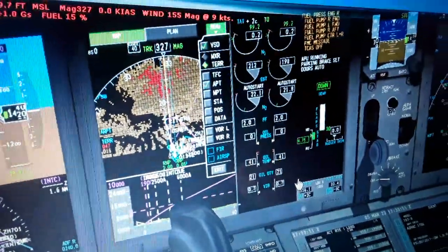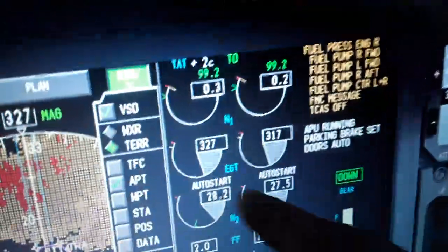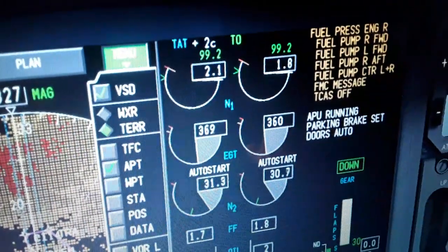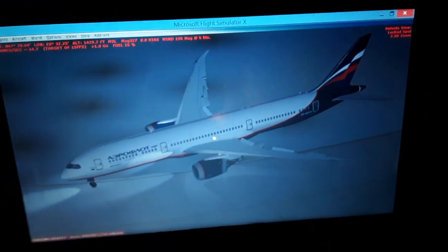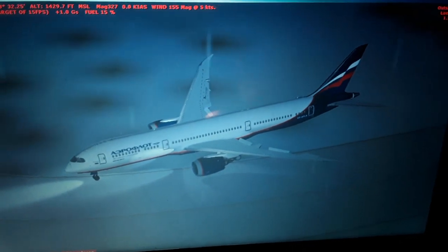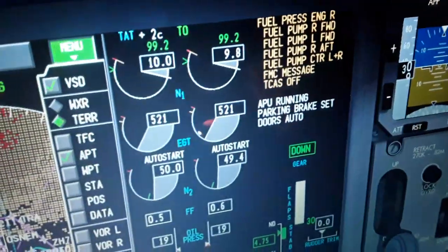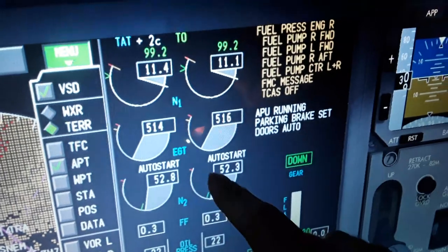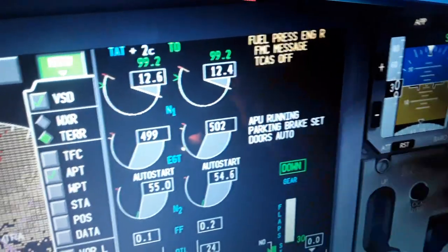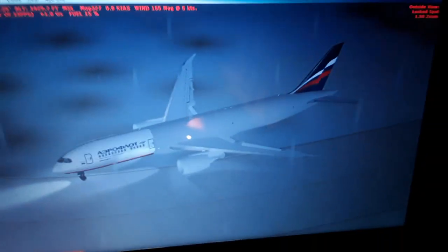So we have about 1 minute to go for takeoff. So auto start proceeds, 28%, 29%. You can see now we have both fuel and pressurization from the APU. So the auto start proceeds. The amber lights off. Now we're gonna see the running engines symbol over here.